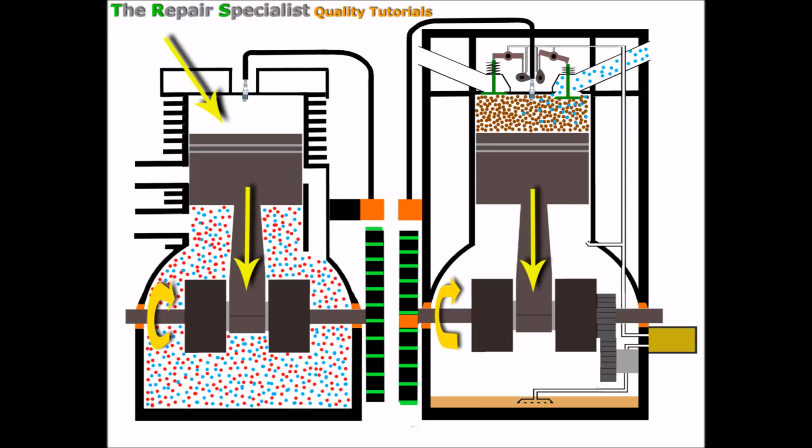So let's have a look at what's going on at the same time with our two-stroke then. Of course, the piston's coming back down, and that stopped the air and fuel from being drawn in from the inlet port there, because what's happening now, as the piston's lowering, it's actually starting to compress that air and fuel down there in the crankcase, rather than there being a vacuum.